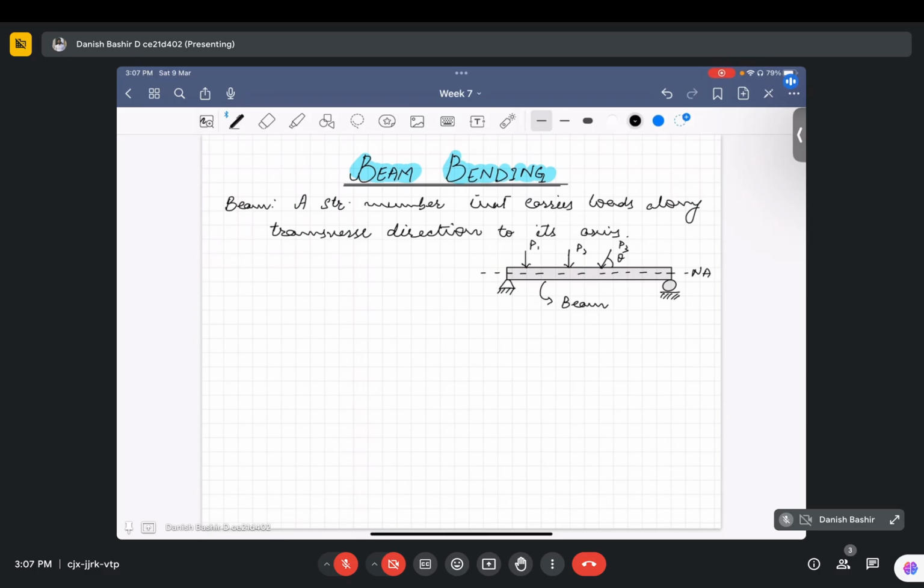In structural analysis 1 and 2, we were given boundary conditions like simply supported, fixed, or fixed with one more support in the middle. These are very simple boundary conditions, and we have classical solutions for them. In finite element analysis we can have different boundary conditions, whatever exists in real life problems, and we can solve those problems. In today's lecture we will first see the formulation, how we deduce the element equation for a beam element, like its stiffness matrix, its nodal force vector, and other things, and then we will solve a problem regarding that.